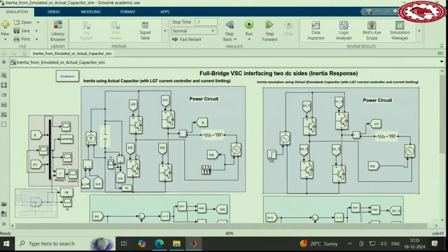So here you see there is a capacitor on the left side of the converter. Here there is no capacitor. It's just a battery, a voltage supply. And this capacitor obviously needs power, right? The power should come from somewhere, but we don't have a power source in Simulink and in other simulation software. But we have a current source. So you can put a current source here and then adjust the amount of current properly such that the amount of power that you want is coming here.